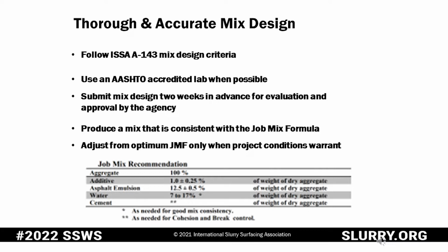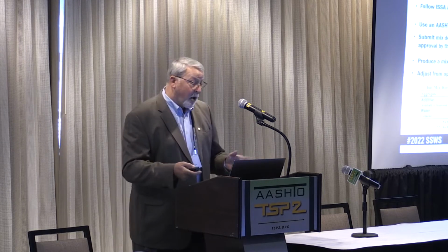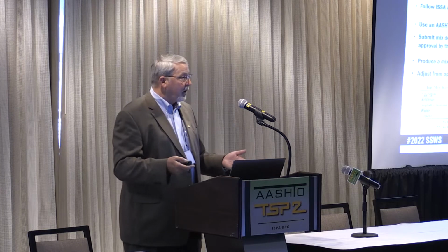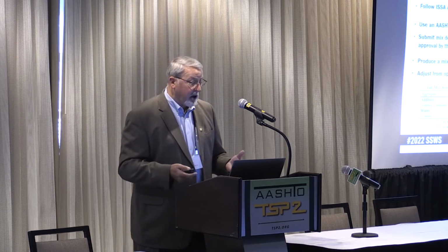And why might you want to run on the lower end of the residual content in a microsurfacing mix design? If you've got a rich asphalt surface, a chip seal that's kind of been flushing or hopefully not bleeding, you may want to run on the low end of that design to allow for some of that migration of that existing free-flowing asphalt up into that microsurfacing, because it's going to come back through.